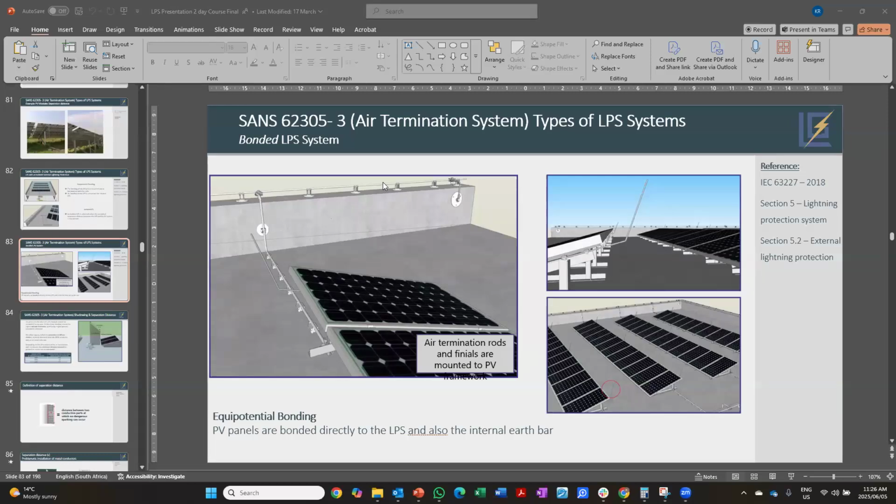So with that video, hypothetically, what happened is someone went and installed the cheapest way. It was the only way to do it. Either they could not install it on the roof, as what I'll show you now, and they decided to put it below the panels. It's quite common in the industry that they do it that way. The problem is that you're basically exposing full lightning currents onto that solar panel. So if one of those panels burns out, it can burn your whole array to smithereens, because it's not 50 hertz frequency, it's high voltage, high frequency lightning currents that come down. So you need to dissipate